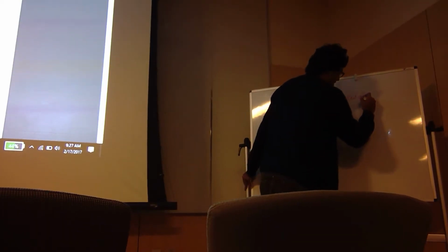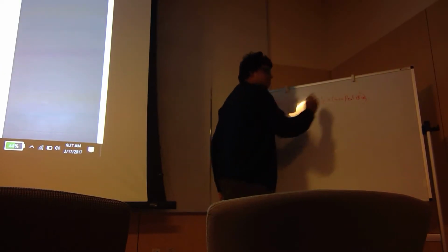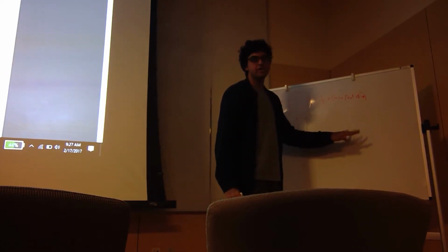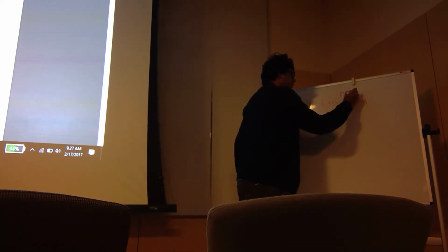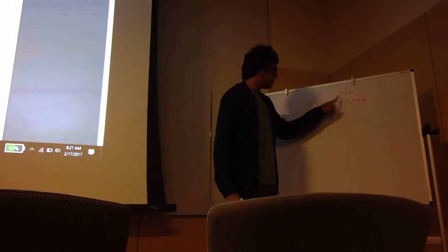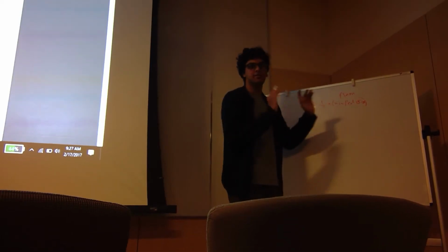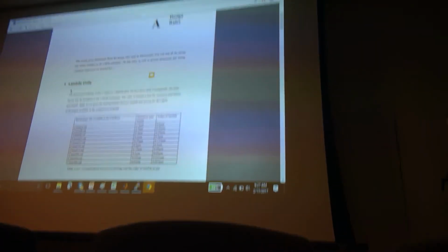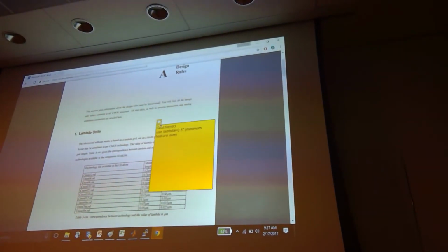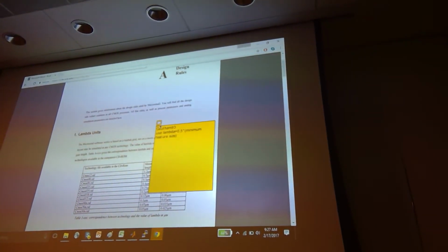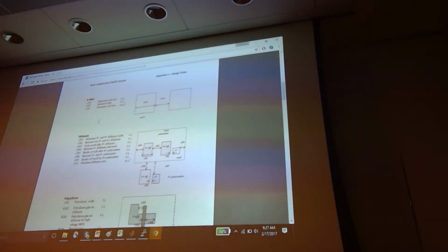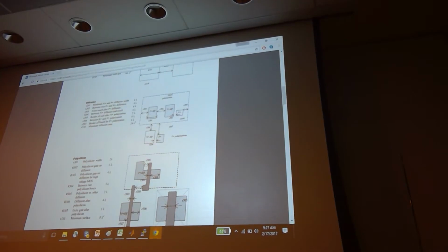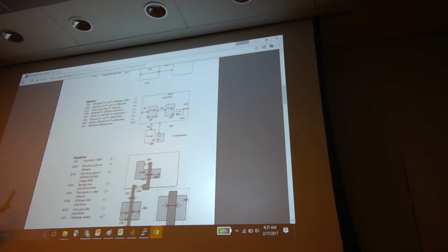And your minimum feature size for 45 nanometer technology is 45 nanometers, okay? So if you decide to use this node, take half of this as the value of your lambda. I put that here, so take half of your minimum feature size as lambda. And this file basically contains all the design rules. So you can just go through this. It specifies everything you need.